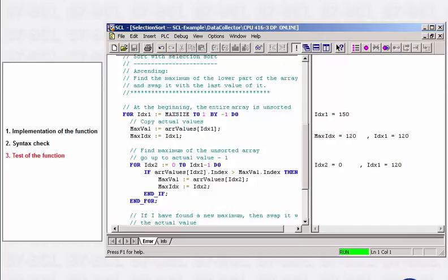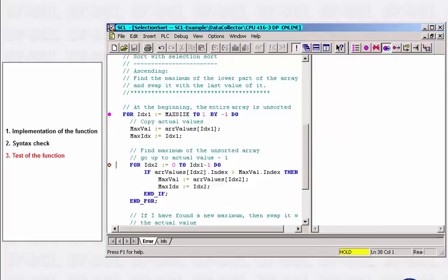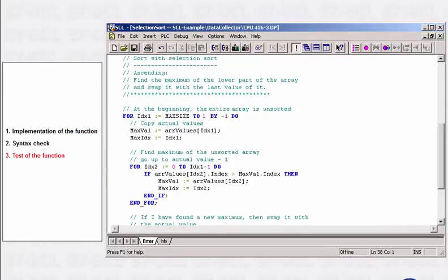In the case of highly dynamic processes, like the one we have here, it is best to use the single-step mode with breakpoints. In just a couple of clicks, the controller will interrupt the cyclical operation at the breakpoints. By going through the code step by step, you can have the contents of each variable on the CPU displayed. The error search is simplified considerably in this way, making it possible to do simple module tests beforehand with S7 PLC Sim, for example. This reduces even more the risk of having to change the code on the plant and can thus shorten the commissioning phase enormously.